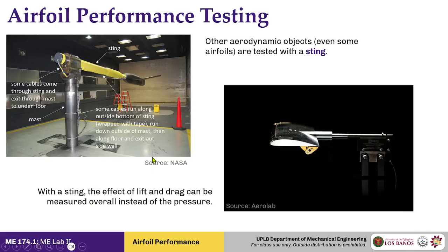Now, this might not have as great of a data as you expected, but it is still useful, especially if you're just after the lift and drag. Basically, sometimes pressure tapping is too complex, you need a lot of taps. Sometimes, if you try to tap a complex object, you might need a very expensive setup. So for sting fixtures, this is more accessible. And sometimes it's good enough for that.